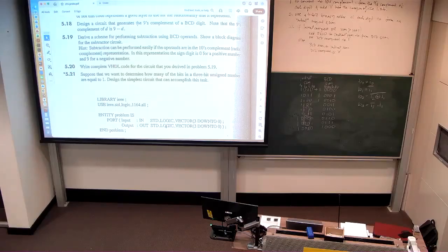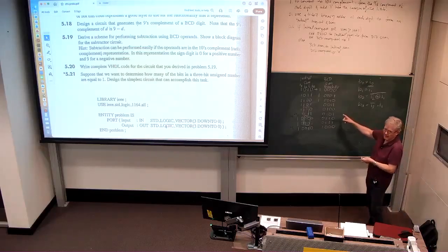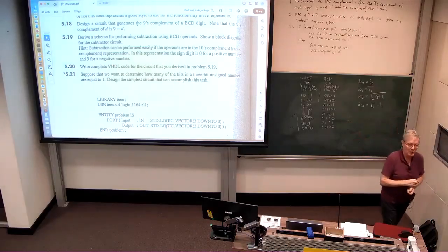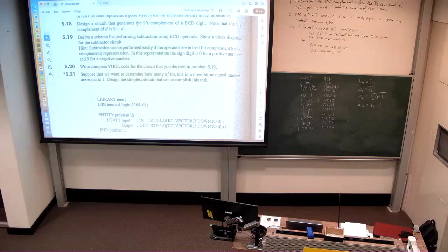So we generally have to use the coefficients of our filters as constants within our circuits and multiply those constants with whatever value has been received on an antenna in order to do the filtering. And it's much cheaper generally to use a specific adder or a specific multiplier than it is to use a general purpose one. And that gives us great advantage in the FPGA. What's more, we can reconfigure the FPGA as those constants change.